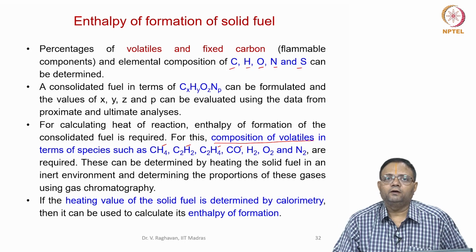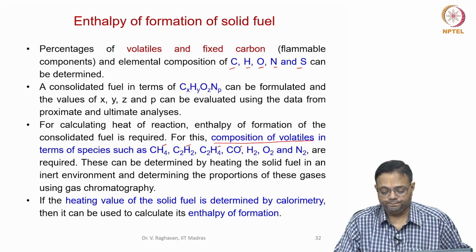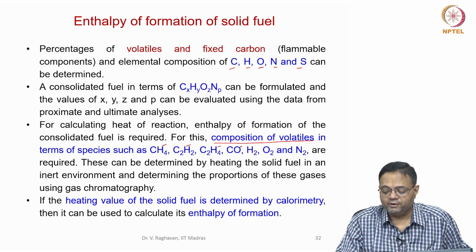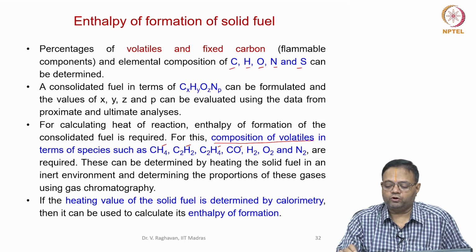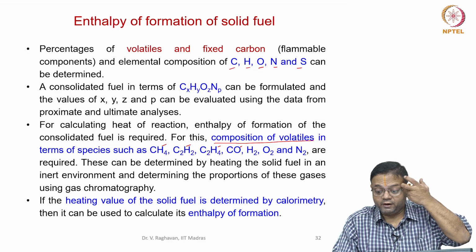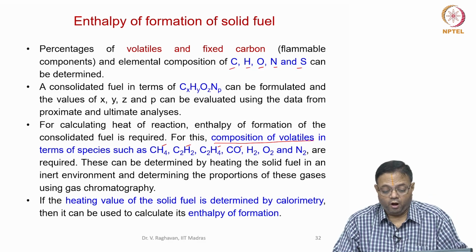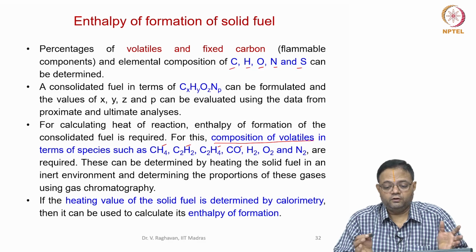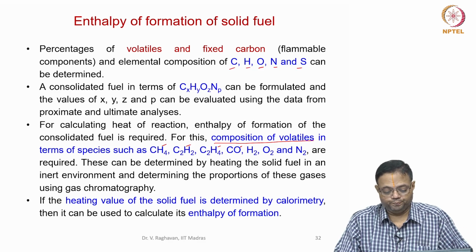For fixed carbon, enthalpy of formation is 0 because it is graphite, a naturally occurring element. So, if the composition of volatiles is available, then only the enthalpy of formation can be found, or else we cannot determine the enthalpy of formation of the solid fuel straight away.